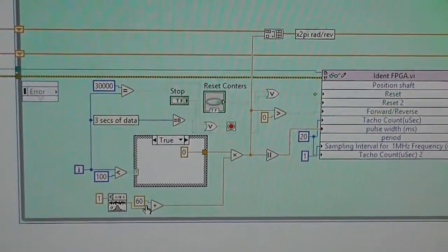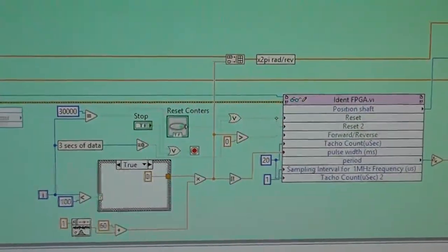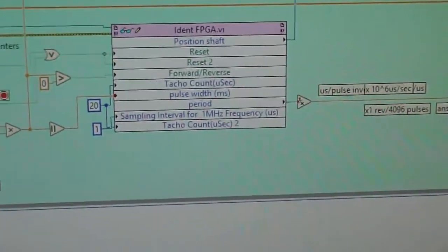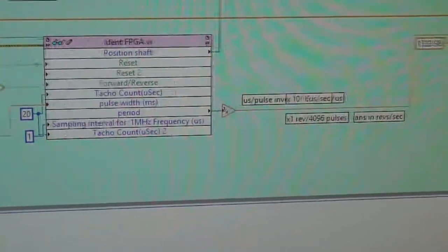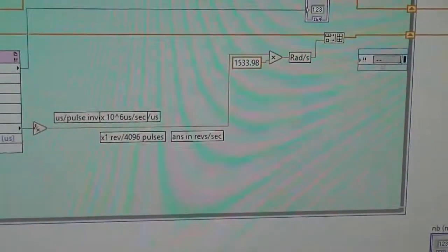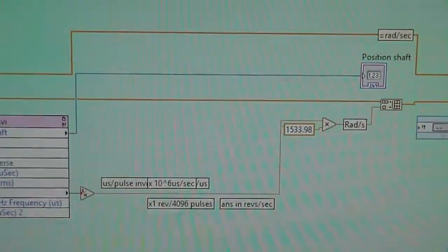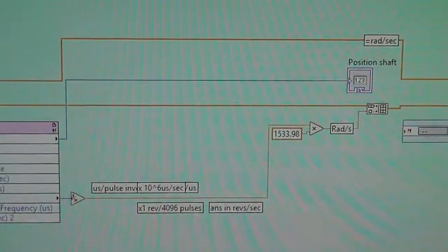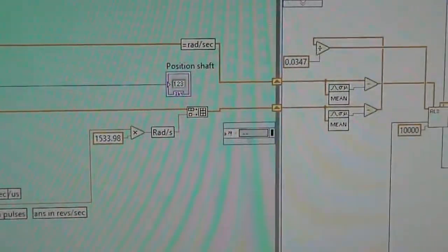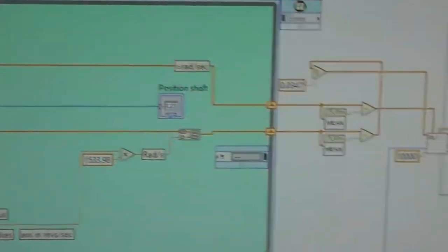Then I measure the speed at the output. So I've got data at the input and the output. Most of that's done with the FPGA. I'm just at the upper level here. It's just gathering the data, and it goes through a real-time loop sampled at 10 kilohertz, and then the loop only runs for a few seconds and stops, and outside the loop is the recursive-least-squares.